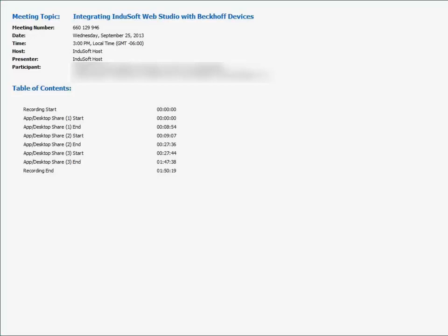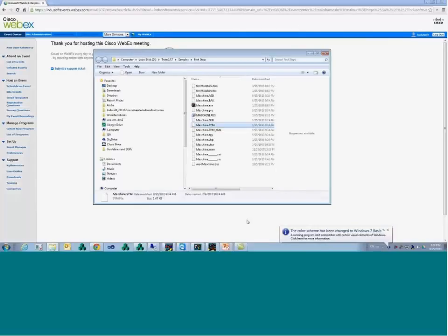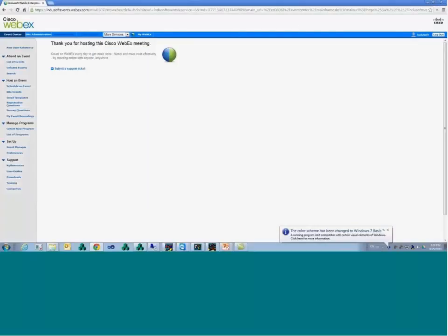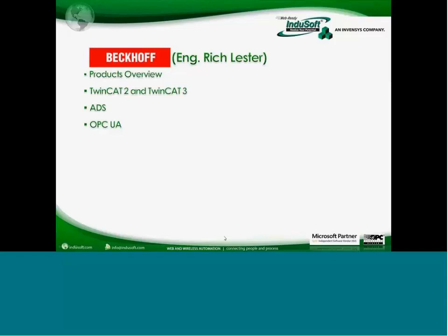So when you guys use that, keep in mind that the lower the processor, the lower the power that you're going to have. And so you cannot sometimes think that you can run a project with, let's say, 50 screens and talking to 2,000 tags on the lowest end processor. That would be a little too much. So you always should size your processor according to your application, because I don't know if you guys got that, but you can run both InduSoft and TwinCAT on the same CPU.